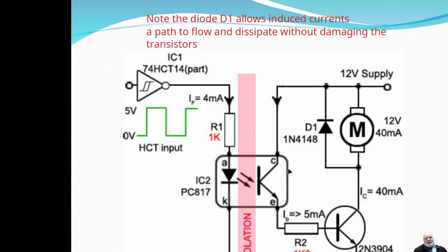Usually it's going to be pretty small, probably less than a volt. But look at the data sheet for whichever optocoupler you have and use those values to calculate what value of R2 to use. In this case, it says 1K2. I think that 2 was supposed to be an omega for resistance. I'm not sure about any of these values on here. They're just kind of demonstrating.